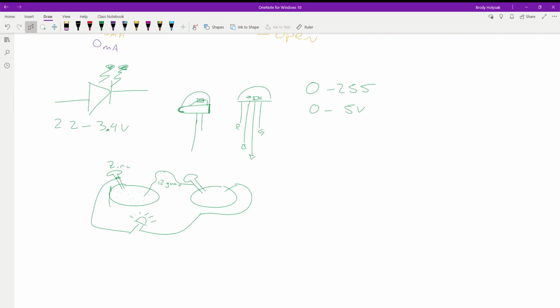The other circuit I built had an LED that would first power on a green one, then the signal went through a capacitor and a resistor because I wanted it to delay. What I was trying to do was get the capacitor to charge up slow. I got it to about 5 seconds. I put another LED across the capacitor. So when the green light turned on, you would count to 5, and then the red light would turn on.